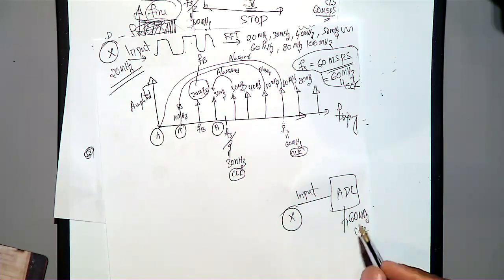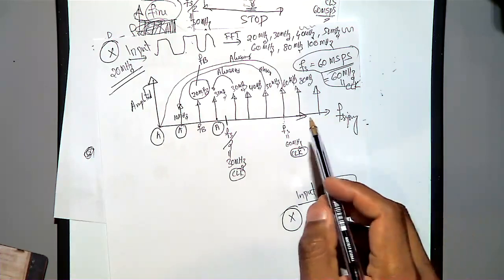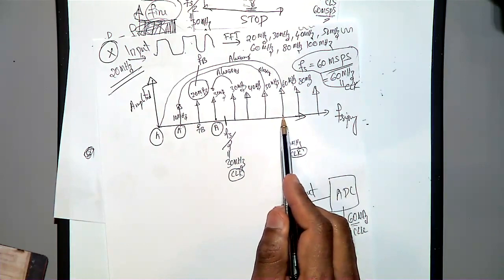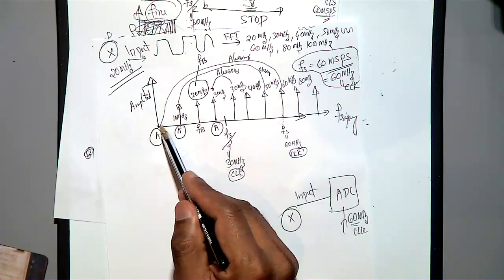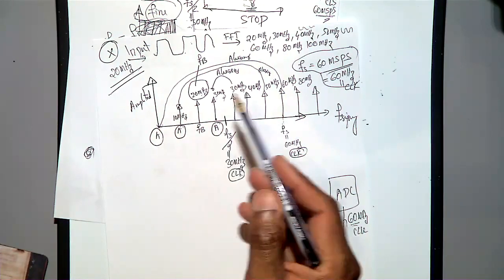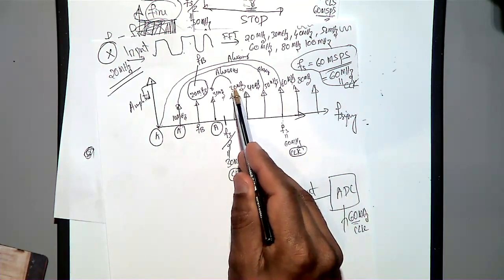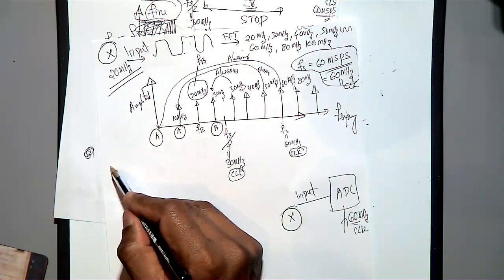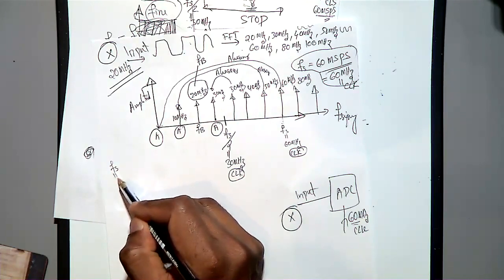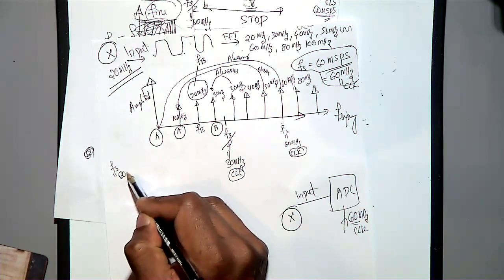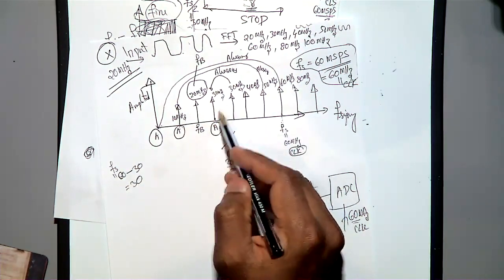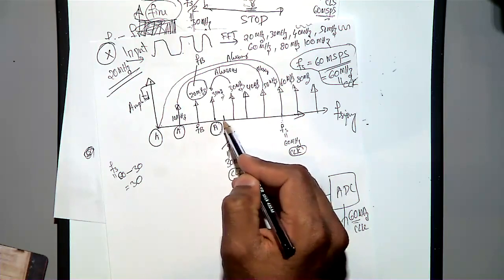Here the ADC clock frequency is 60 megahertz. Even if you have 60 megahertz in your signal, when it is sampled it will be a straight line. There is no frequency, so that appears here, and you don't have much issue with that one. But when you have 30 megahertz, you can easily find where it will come. Your sampling frequency Fs is 60 minus the frequency 30, so it folds back. That is the reason for aliasing. So it will come here.